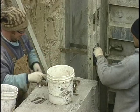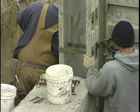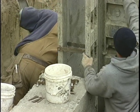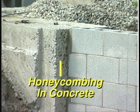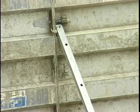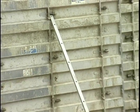For quality work, the forms used must be tight, smooth, defect-free, and properly aligned. Any leakage out of a form tends to weaken the wall by causing honeycombing, a problem that occurs when air pockets form inside the concrete. Wall forms must be strong and well braced to resist the side pressure created by the fluid concrete.